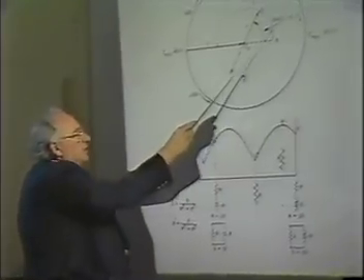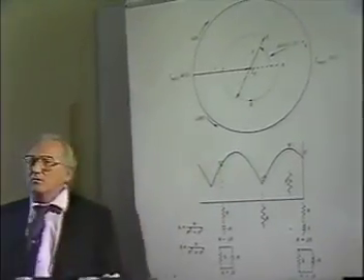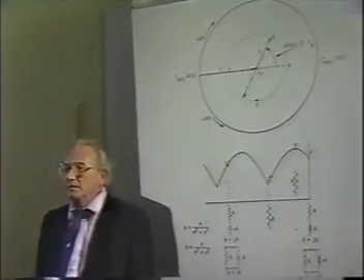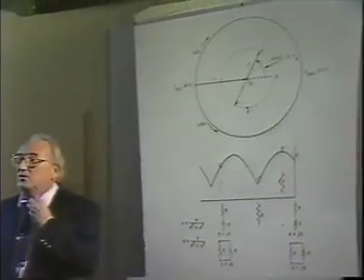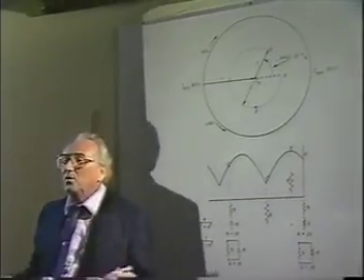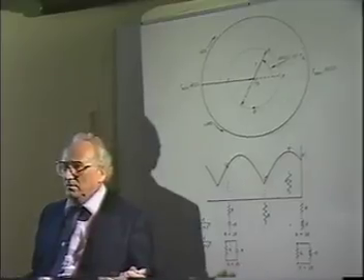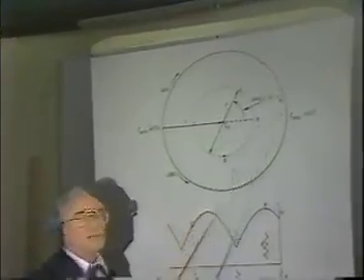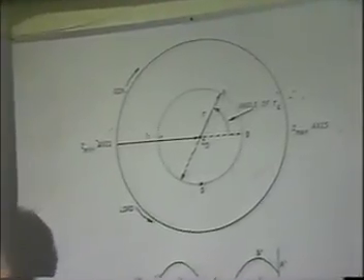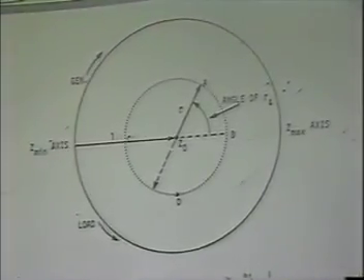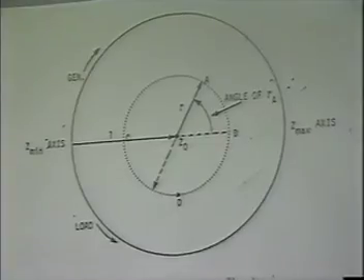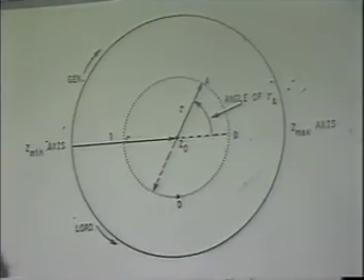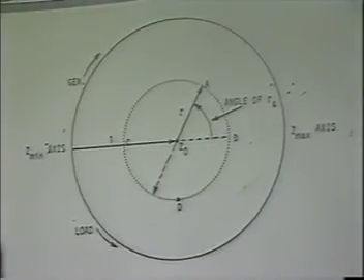I told you that this circle here is called what circle? When it's discussed, or when it tells you to draw that circle, it's called the VSWR circle. It's convenient because along this axis on the chart you read the VSWR right there in numbers. Could I also call this the gamma circle? Why not? Because gamma is a radial scale parameter, isn't it?